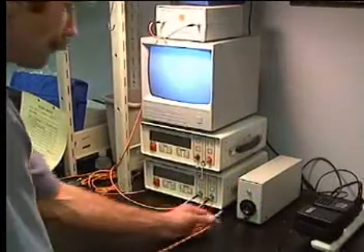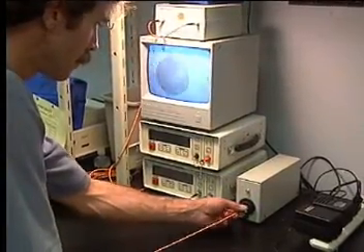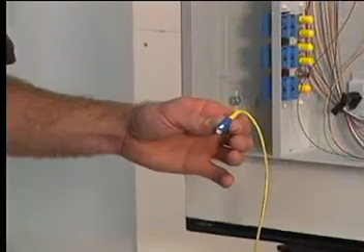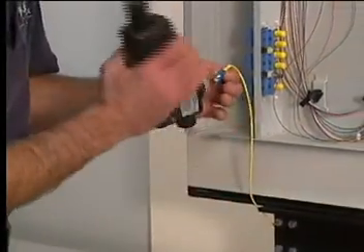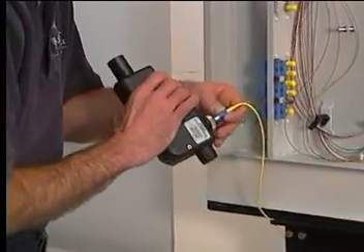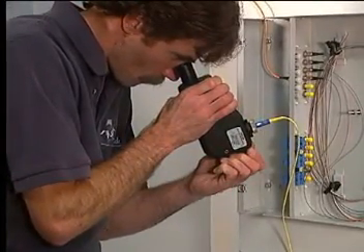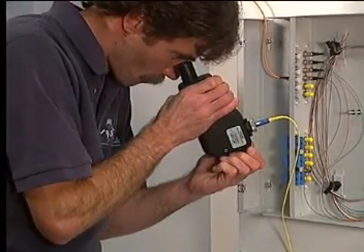One way to tell is by rotating the connector while viewing. If the contamination rotates, it is on the connector. If it remains stationary, the dirt is in the inspection scope. When you see a clean connector, immediately reinsert it into the mating sleeve or bulkhead. If the inspection scope indicates that the connector is still dirty, repeat the cleaning procedure.